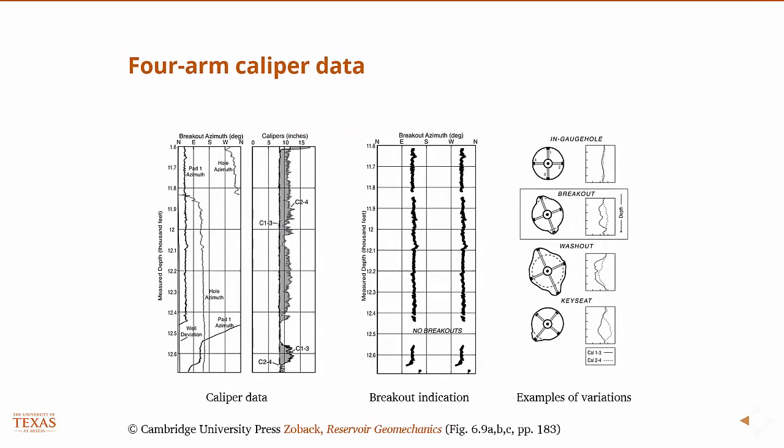However, it is very important to not misinterpret the data, because breakouts are stress-induced. Okay, so when we talk about breakouts, we're talking about the fact that the in-situ stress exceeds the strength of the rock, which causes a breakout. But you can also have other damage to the wellbore, or other scenarios in which the wellbore is not the size of the drill bit, right?